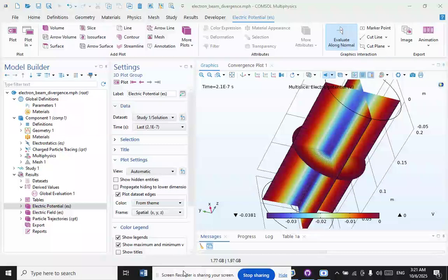It is shown that changing the focal position from being located at the top surface of the substrate to being located at mid-depth or at the bottom surface, a full penetration thermocapillary can be generated instead of a partial penetration thermocapillary, demonstrating that under-focusing of the beam is a crucial component for successful EB welding procedure development.